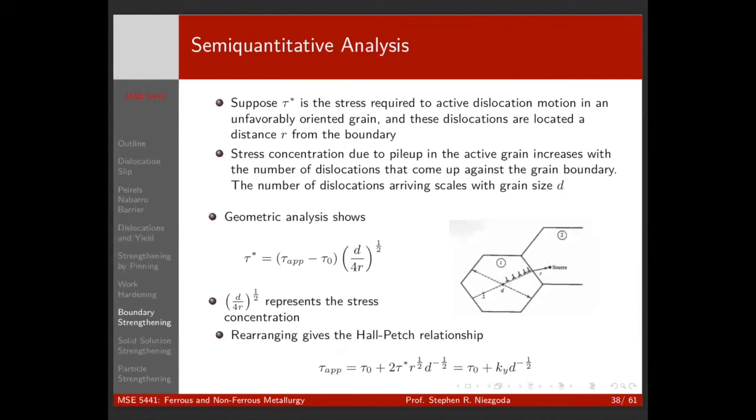And so we start deforming this grain plastically. This grain is still elastic, right? We haven't activated any dislocations here yet. Schematically, we can think about dislocations piling up at this interface, right? And we can calculate what the stress concentration due to this pileup is, right?